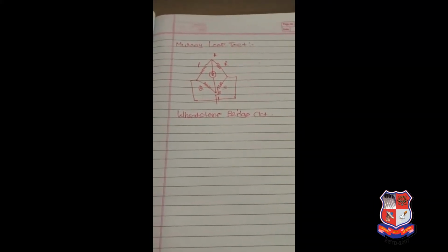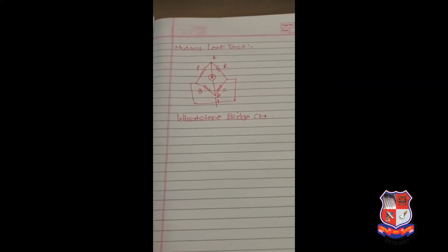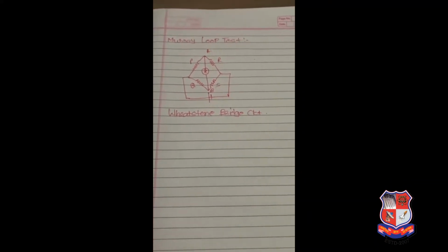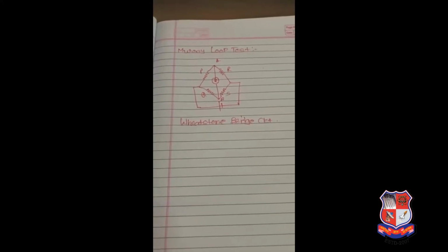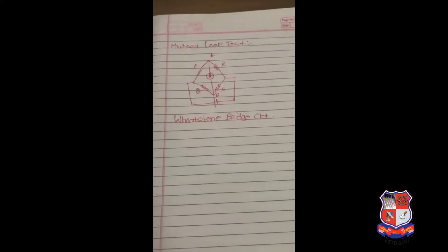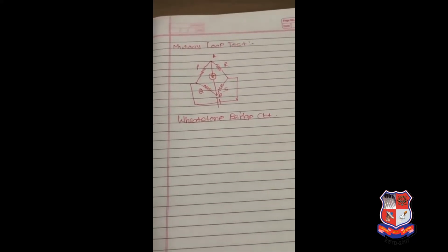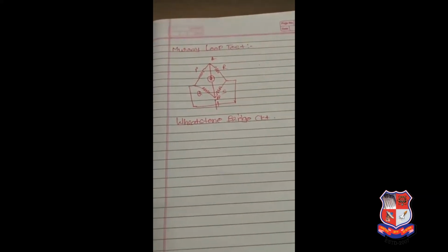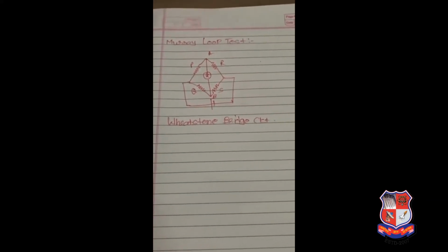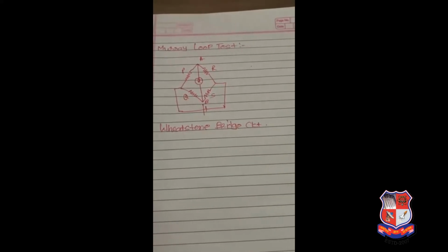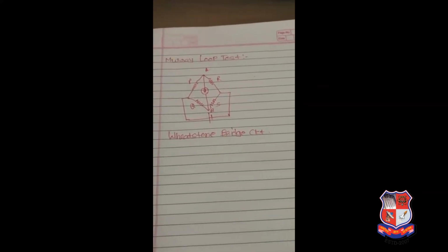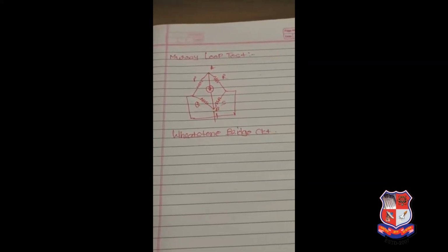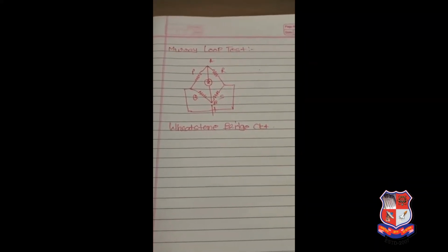Hello students, in this video lecture we will discuss the Murray loop test. The Murray loop test is used for finding the fault in underground cable. This test is useful only for shunt faults, like a short circuit between the conductor and earth or between the conductors. The test is not applicable for open circuit faults.